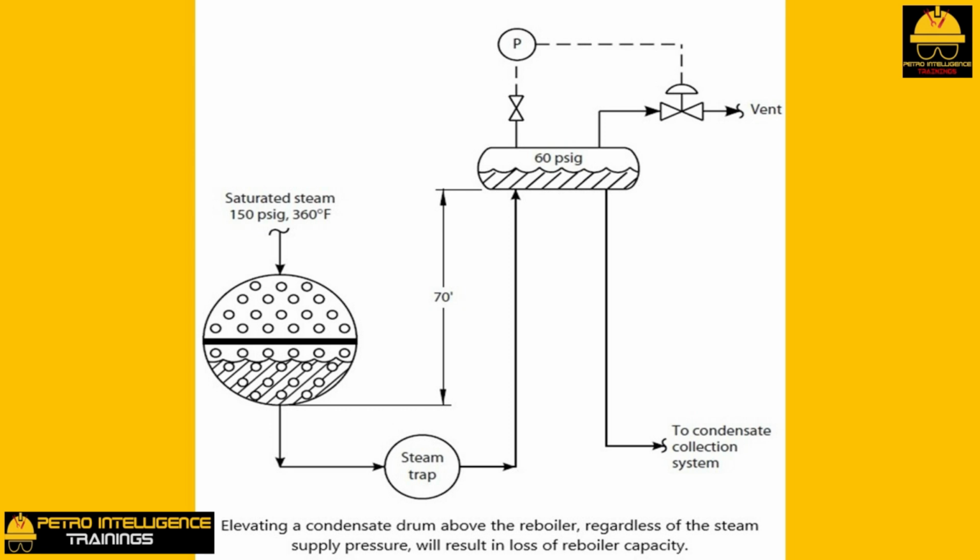But it will not. The problem is that the condensate rising from the steam trap will begin to lose pressure due to the gain in elevation. As it rises above the reboiler level, the hot saturated water will start to flash, undergo vapor lock as described previously, and thus choke off the flow. The condensate will back up in the channel head of the reboiler shown in this picture and become subcooled enough to suppress steam evolution until the condensate enters the drum.